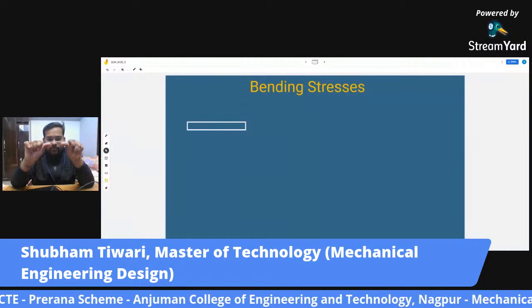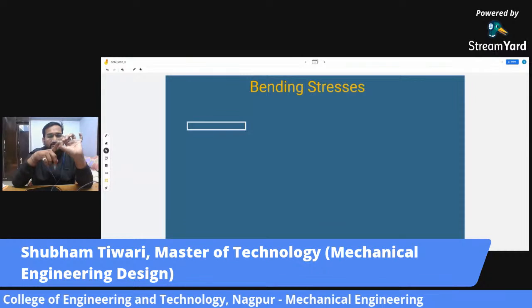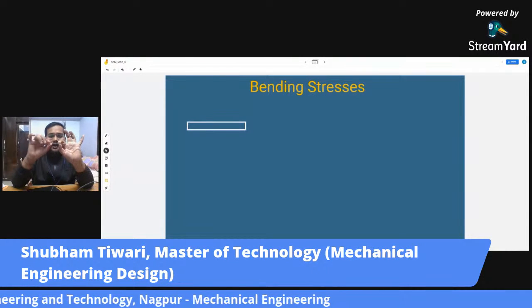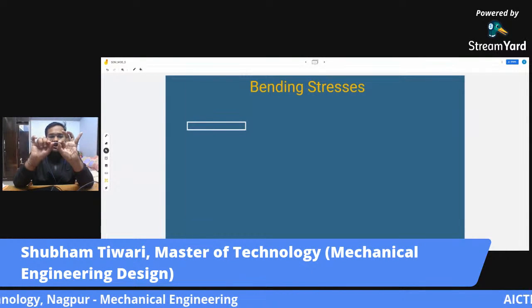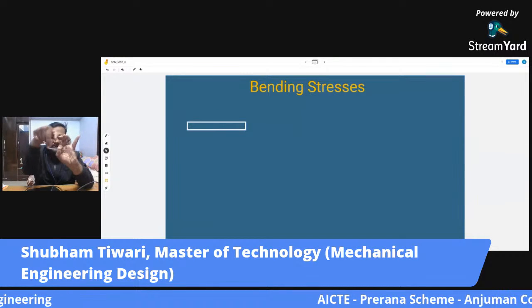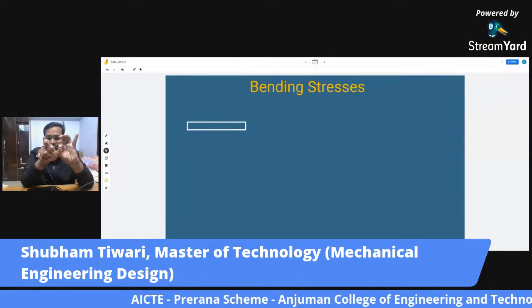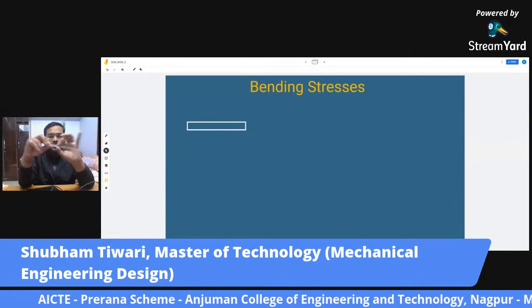So these two supports are very necessary for bending it. This is a fixed support here, and then I apply a force down here. There is this perpendicular force and this distance. So distance into the perpendicular force, or force into the perpendicular distance, is your moment.